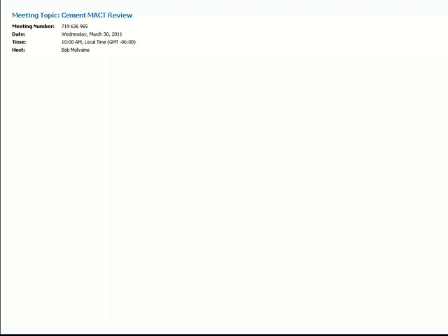Obviously, opacity monitors are doing that, and it's ridiculous because you're measuring in the middle of the process. But now we've got a new PM mass monitor standard, and I guess the question is whether there is the same flexibility. Yeah, you can measure it before the scrubber, after the particulate device, because that's where you don't have any water vapor.